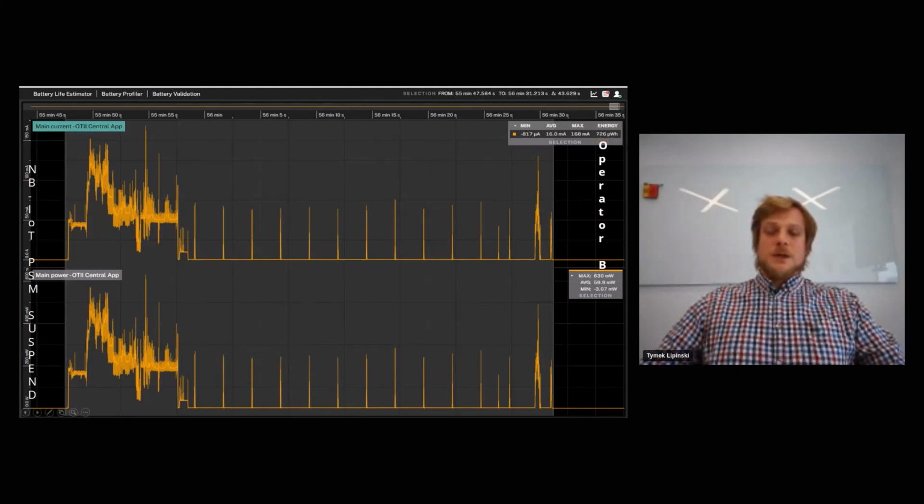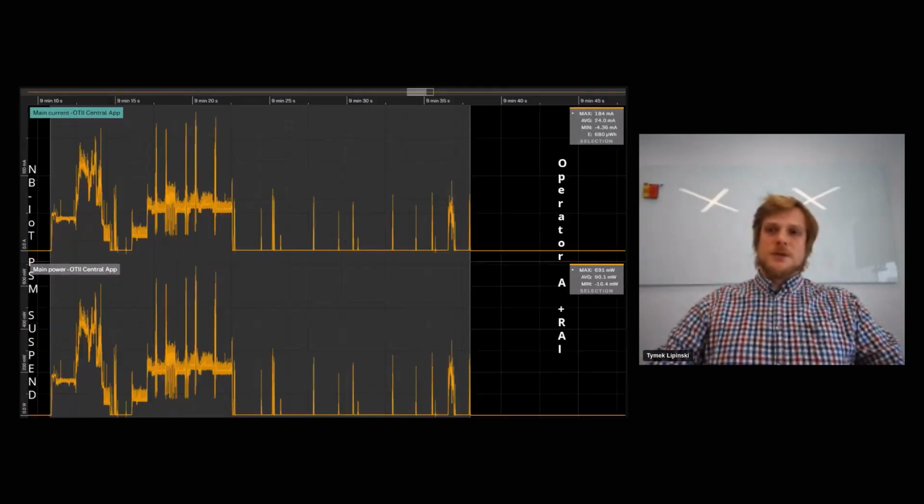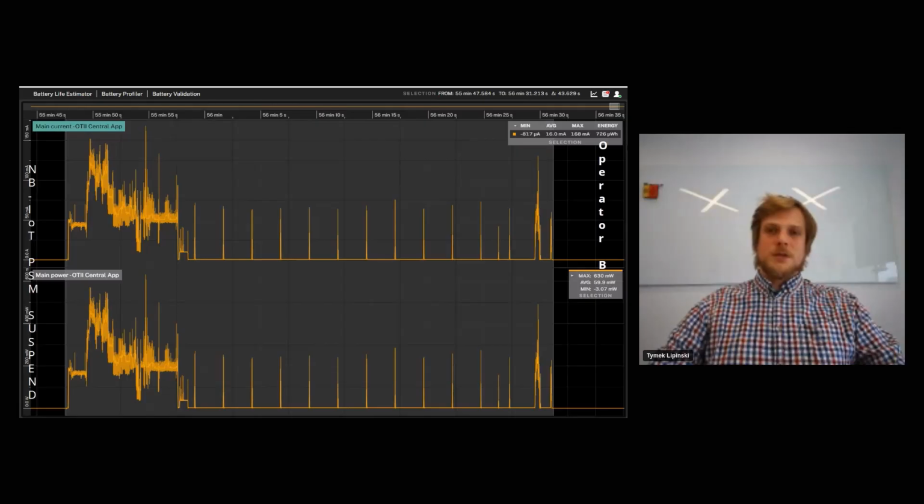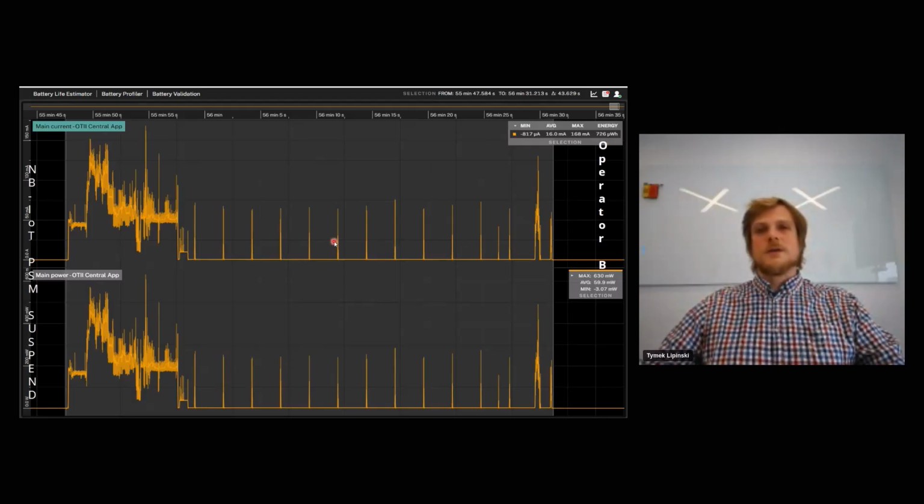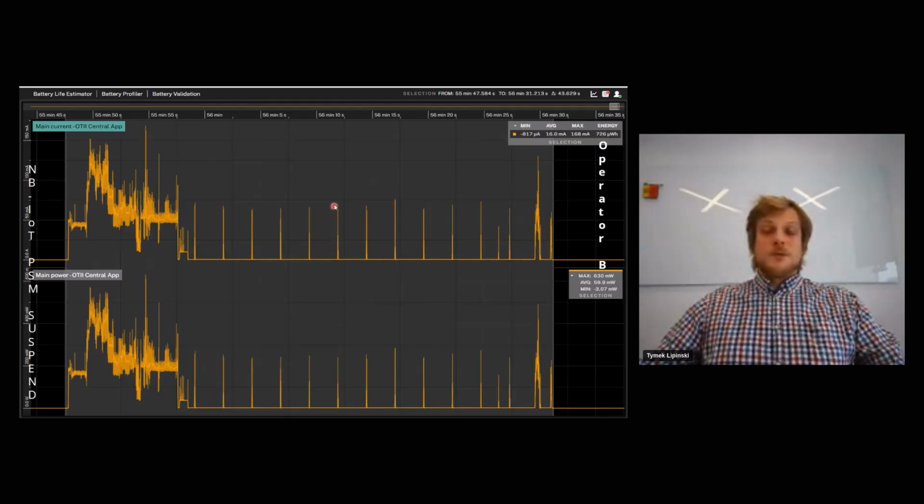So 1 second RRC of operator B versus release assistance indicator: 680 versus 76. But please note that the active time here was very, very long. If we make it shorter via the requested PSM timer configuration, we could easily go below 500 microwatt hours per such cycle.